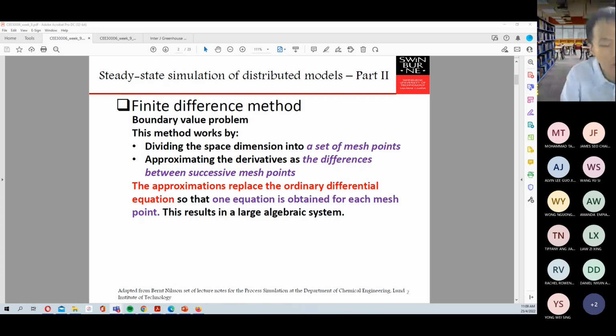So it's very important because later on, if you try to solve the steady state lumped model, transient lumped model, or you try to solve a steady state distributed model, or the transient distributed model, then the numerical methods will be totally different, right? So it's very important that you really know which among the model classifications you are dealing with. That's why in process modeling, I give you material where the coverage is based on the different models. So we split based on steady state and transient, and we also split between the lumped and the distributed model.